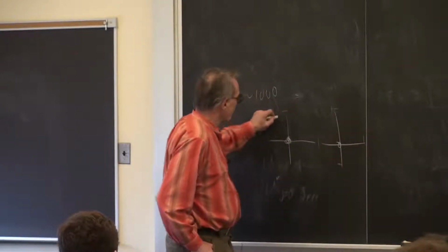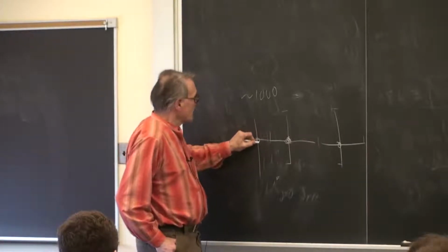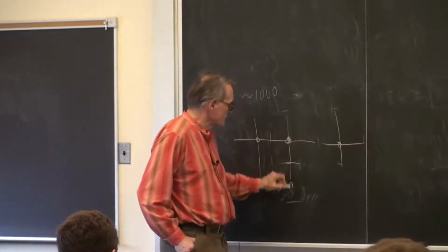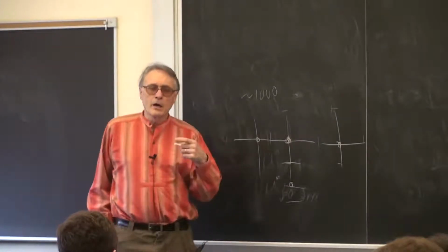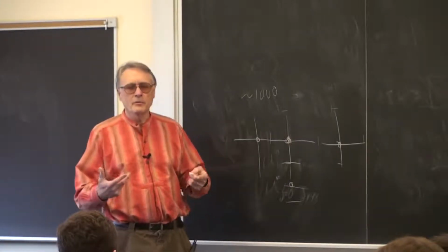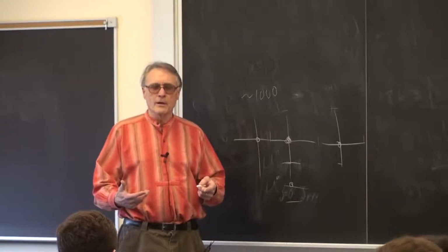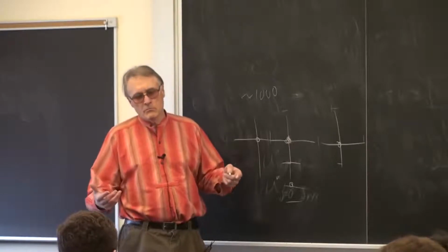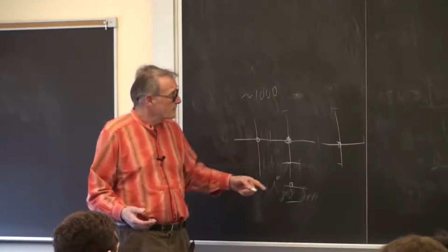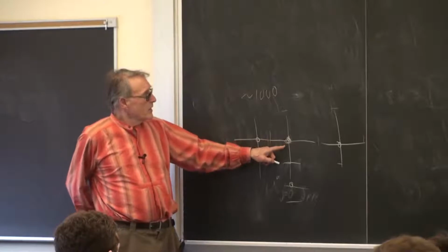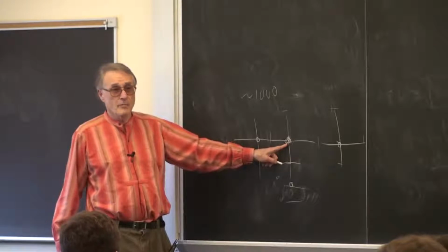Then, let's say that you build a state machine that uses one multiplier to step through 5 or 6 steps. You can actually do it in probably 2 states, but 5 or 6 steps, or even 10 steps, then 99% of the time those compute nodes are going to be sitting idle, waiting for the next audio sample.